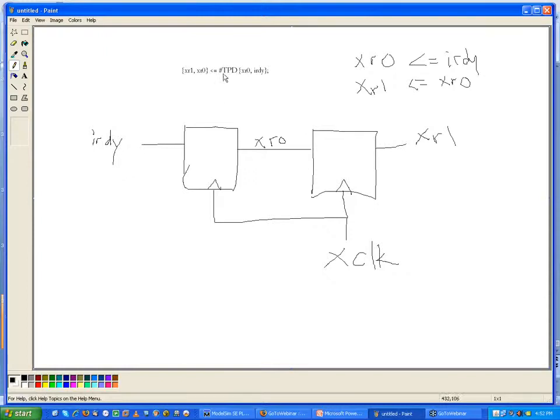Now you'll notice I did have this delay, and this TPD is a parameter that I can change. And it's okay to put these into your RTL code. It will ignore them, they don't actually get synthesized. I use this for simulation purposes only, so you can ignore it for synthesis. So basically this is what I've done for this particular statement. Does that make sense?